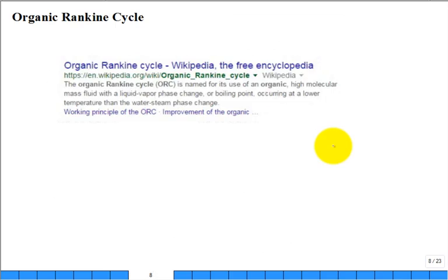We're done with that. Let me hit a couple topics. Sometimes you'll see this term, organic Rankine cycle. Well, what's that mean? Basically, instead of water, which is an excellent working fluid, you use some sort of organic compound or substance. A good one is a refrigerant, because just like if you studied organic chemistry, it has carbon in it. Does water have carbon in it? No. It's not an organic fluid, right? But if you have refrigerants, they typically have some carbon, so they're organic fluids.